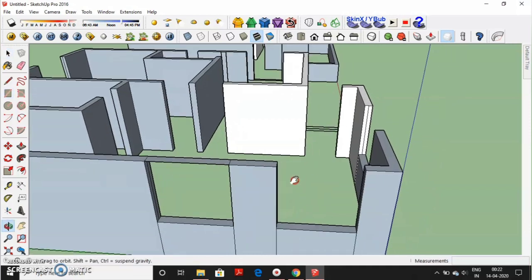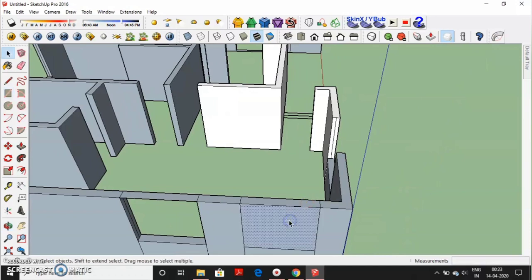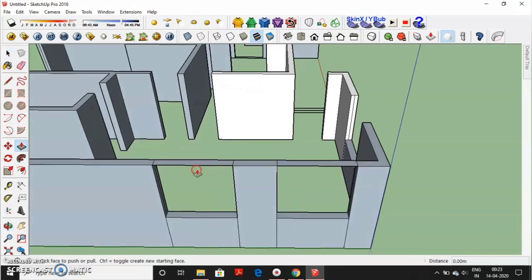Again I will show you the rectangle command R, first diagonal point, second diagonal point, press it. Select the unnecessary surface, delete it. Now I will set the sill level. Now you can press Ctrl to make solid surfaces. I will set the lintel level 2.14 meters. So to set the 2.14 meter, I will subtract it from 3 and I will get 0.86.